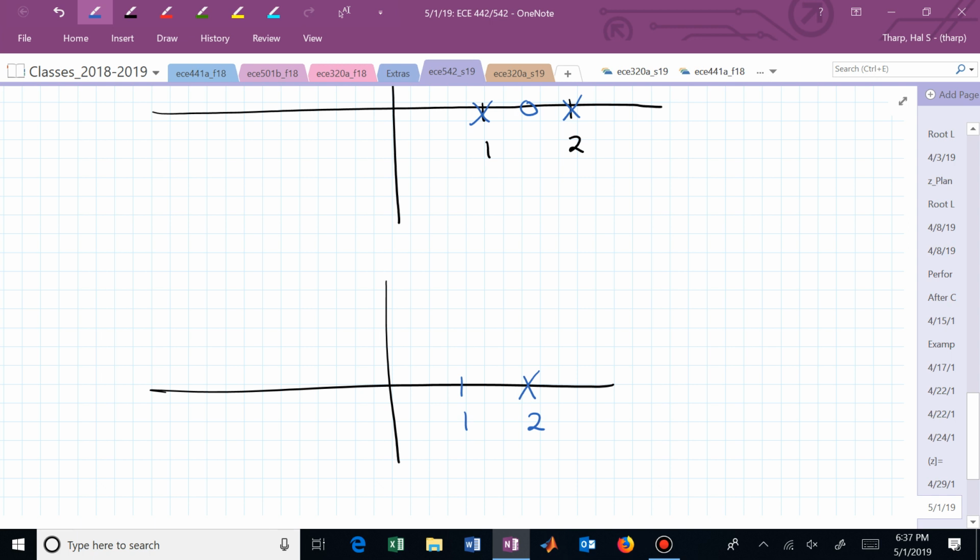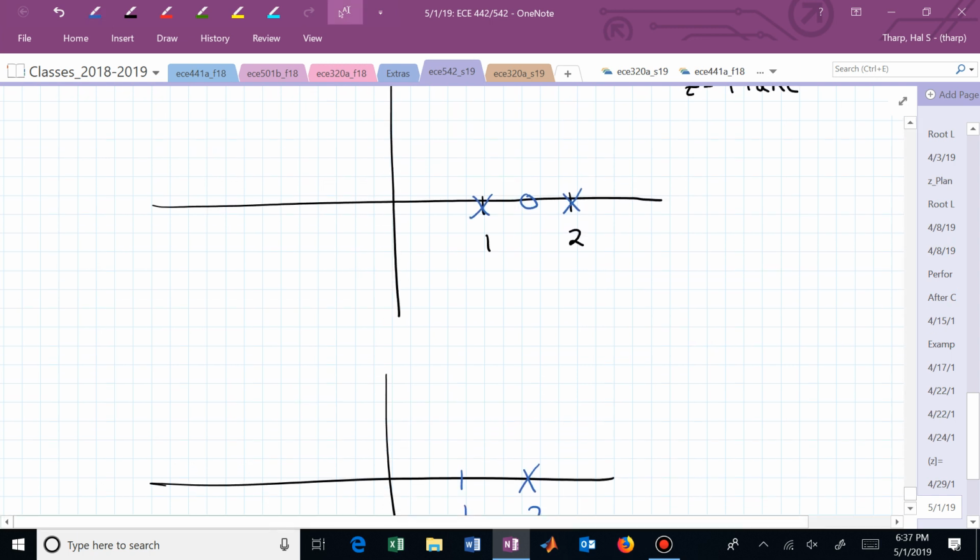But anyway, you could stabilize this one, correct? This one you can stabilize with constant output feedback. You have to crank up the gain enough to get you into the unit circle and not too much to get you out. Okay, but that's not my problem, Dr. Tharp. You gave me this one. So how do we do it?